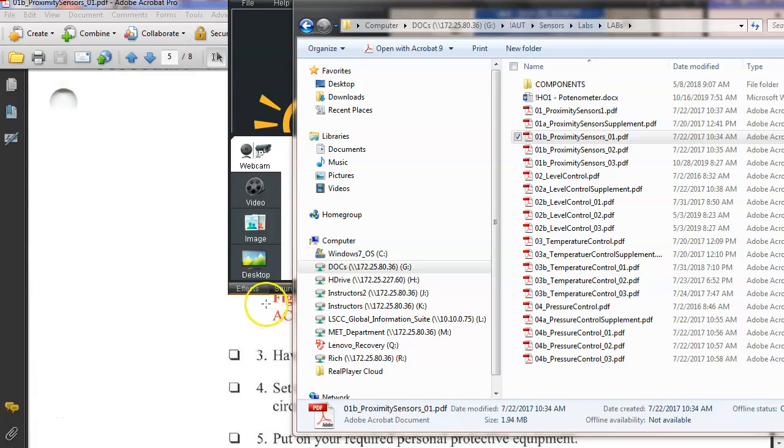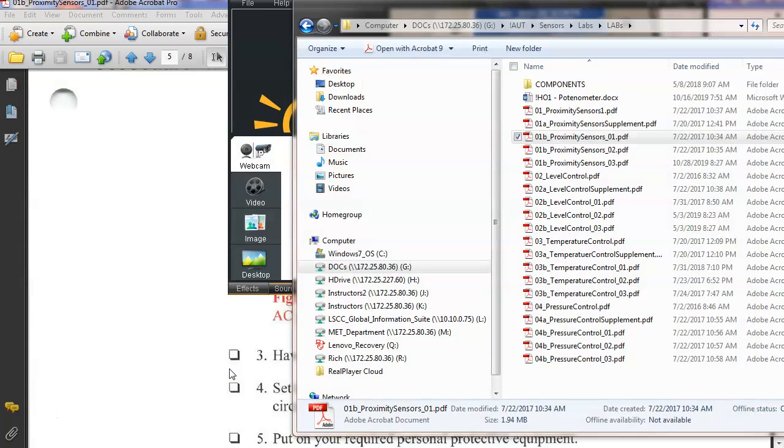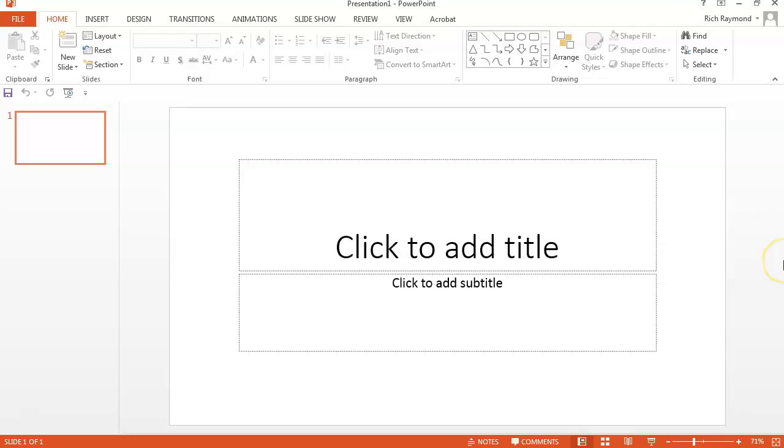and we talked about this, and some of the things we're going to have to measure are in the data sheets. When you replace these things, you might not replace it with the same sensor, right? You understand, but you have to make sure that the sensor you replace it with has either the same or better specifications. And this is an inductive sensor, which means this guy's going to sense what? Metals, yeah.